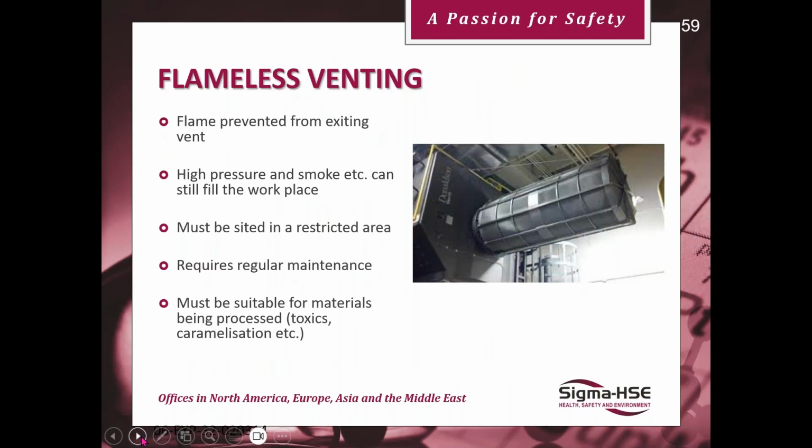So the flame is prevented from exiting the vent. High pressure and smoke can still fill the workplace. It must be sited in a restricted area. Don't just put them anywhere. One I saw faced a lift. It requires regular maintenance. It must be suitable for processing materials that are toxic, prone to caramelization, etc.